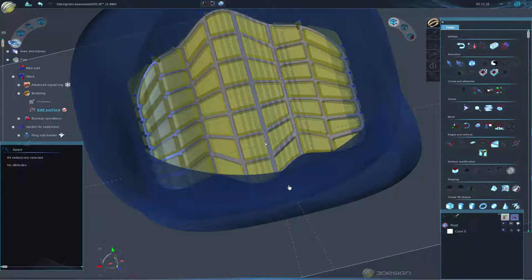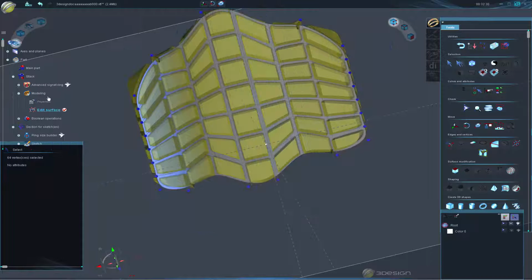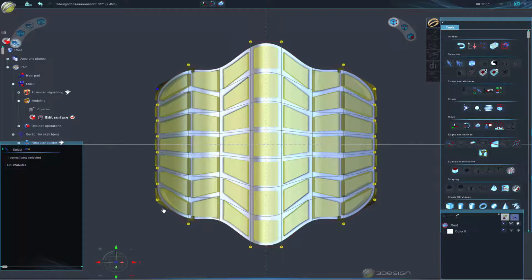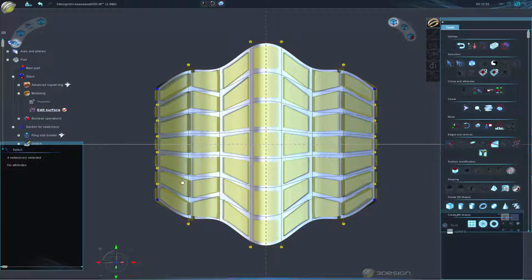Go into points here. Let me hide some things. Okay, you can select these points, and the only new tool which was created for this very purpose is in your edges and vertices section. You have a transform a vertex into a point, so that will create an actual point there instead of a normal vertex, sharpening your edges. So if we recalculate that, we will see those corners become points. Now, sometimes your mesh shape will have, like I said, when you're booleaning it together, you're going to have some weird results, parts of your model.